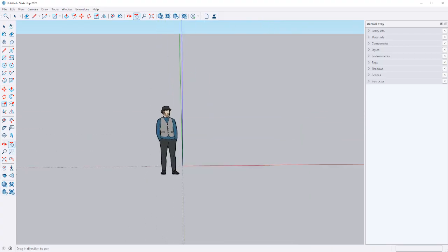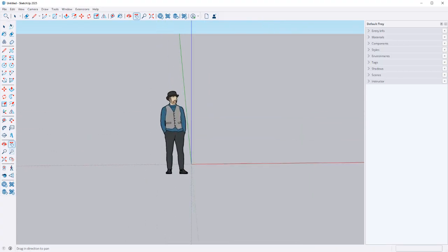All right. Let's talk about selection too, just like in AutoCAD. You can hit spacebar in here and it'll bring up the selection tool. Just like in AutoCAD, the left to right select is different from the right to left. So if I do a selection across this guy and I don't fully circle him, then it won't pick him up. If I do right to left and grab even just a sliver of the hair of his hat, it will select him. I have to go all the way around things. Now, there are different times where we can leverage this, and I might mention some of it in a lecture.